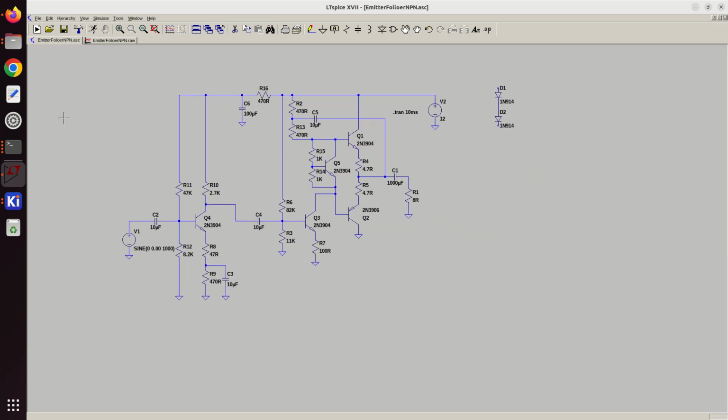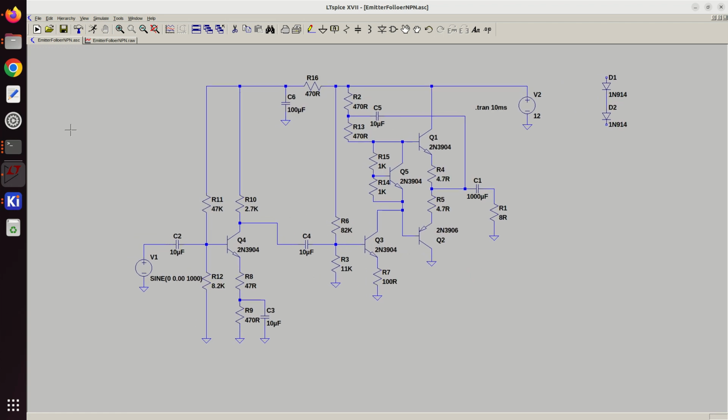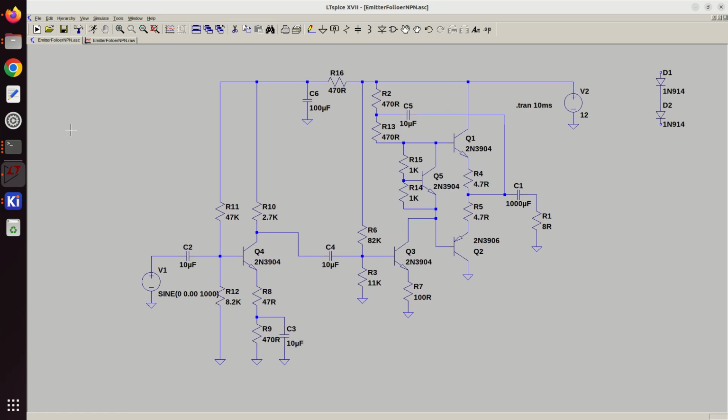Okay, I'm going to cut it at that, folks. But nice way of designing a Class AB audio amp without any calculations whatsoever. And the only other thing is we should put a pot here in reality, so that we feed it in and we can adjust the volume. Then strong signals will obviously overload this, so we can adjust it with the pot.